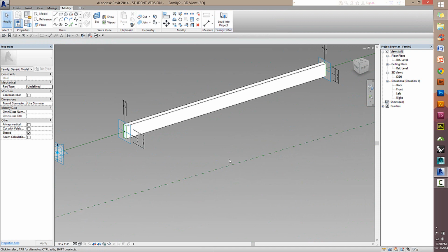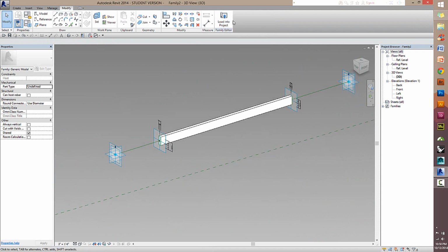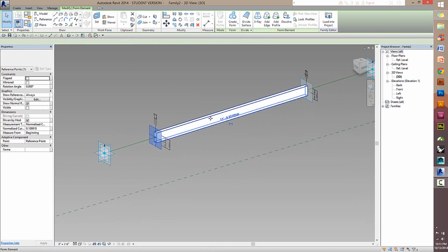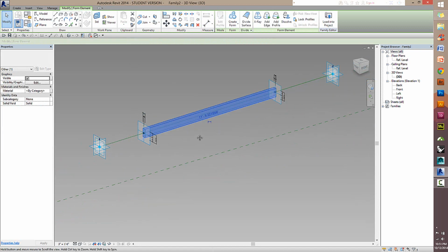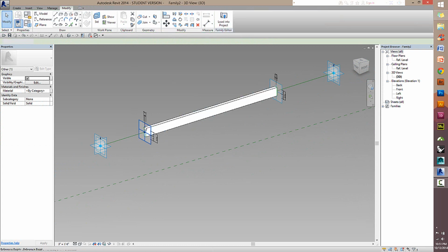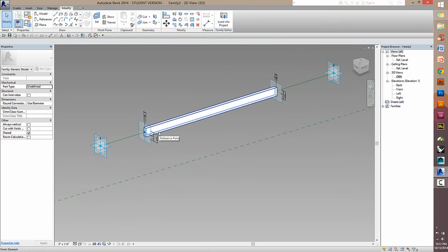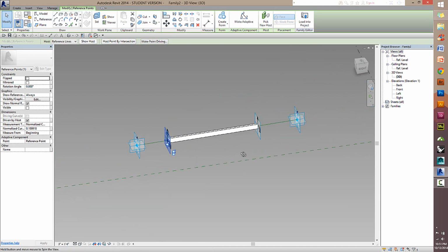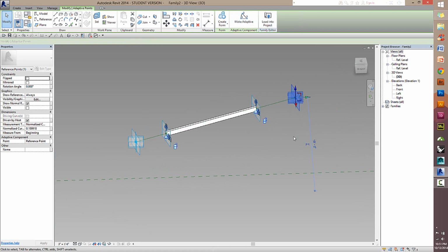It may also be a blend shape between the two. Again, one of the reasons why this all-powerful Create Form button here is not always the best is because you don't always know exactly what kind of shape you're making. But I know that this one works, and that's a good way to make it, by having two curves parallel to one another.